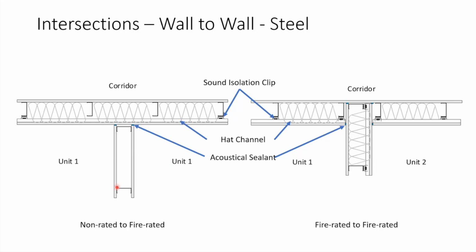If this is a wall between bedrooms, maybe it doesn't really matter. But say this is also an acoustically rated wall, but not fire rated, like an office tenant on this side and a different office tenant on this side. So there's a fire rated wall between them, but you also want acoustic separation between these two offices. Then this is a potential weak path here. And perhaps you could put basically a control joint, a little gap in this, and seal it inside of this wall. That's a detail though to check with your local AHJ to see if you can do that for fire.